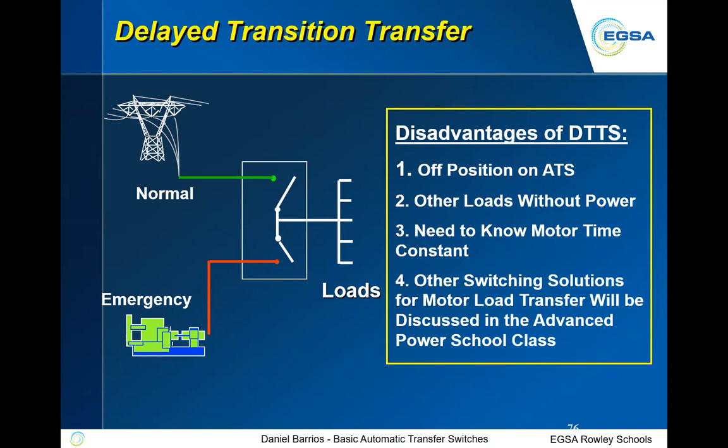Okay. So the point to this is the fact that when it's correct, you use it. In any emergency system, life safety, any load that needs to be reconnected within 10 seconds, you will never want to put this switch, this design switch, in that application.